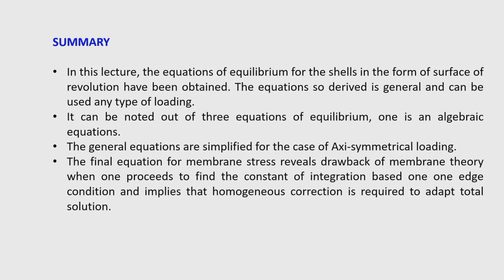But we simplified these three equations in case of axisymmetrical loading, taking the condition of n phi theta equal to n theta phi to be 0, and the three equations are reduced to two equations, and out of that we find that one is an algebraic equation, and the other is a differential equation, but it is an ordinary differential equation.